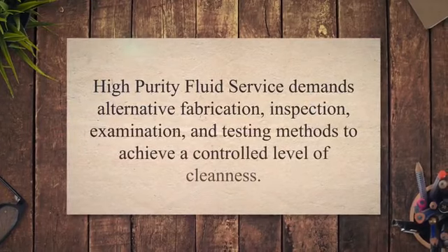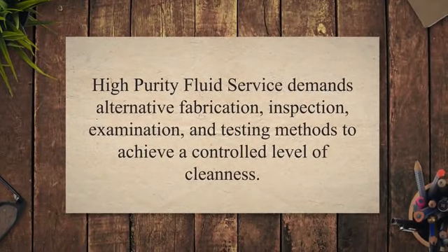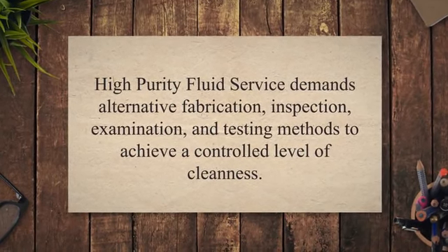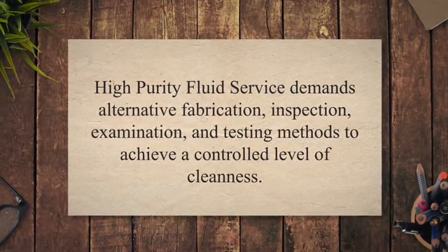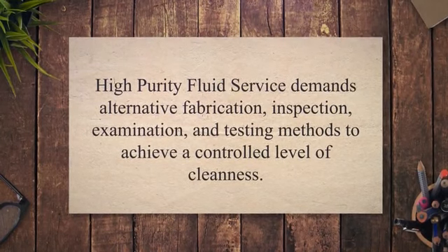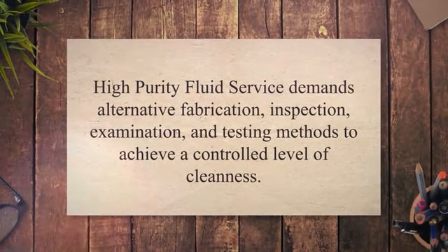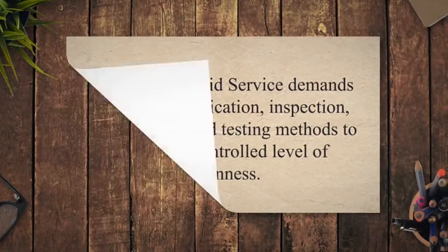High-purity fluid service demands alternative fabrication, inspection, examination, and testing methods to achieve a controlled level of cleanness. The term applies to piping systems defined as high purity, ultra-high purity, hygienic, or aseptic. Guidelines for piping systems with high purity fluid services are added in Chapter 10 of ASME B31.3.